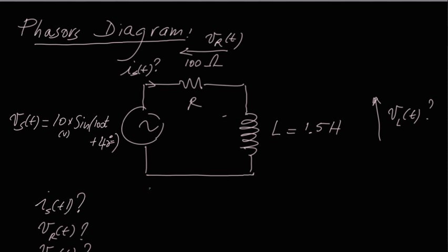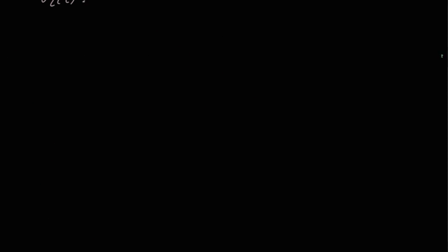All right? Well, instead of doing the analysis in the time domain, we're going to go to the phasor domain. So what I have in here is the time domain. That means the voltages and the currents and everything depend upon the time. And now we're going to switch everything to the phasor domain. So here's what happens in the frequency or the phasor domain.